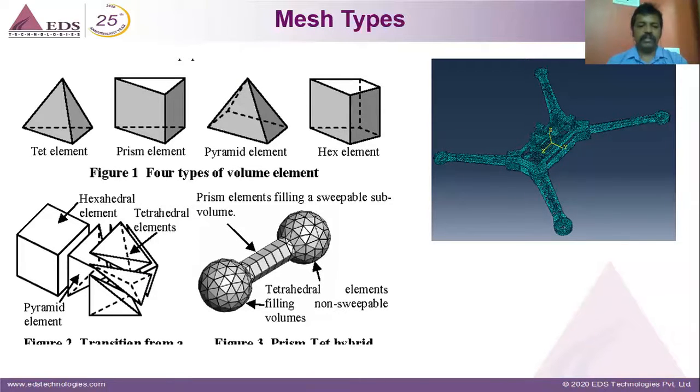So coming to meshing, because I had stressed the meshing part, meshing is very important. Meshing is nothing but you are trying to break a geometry into known shapes. Okay, what happens if you break it into unknown shapes? You will not be able to calculate the area, volume, and all those things. So you break it into known shapes, but you also see that the shape is maintained in connection with the 3D.